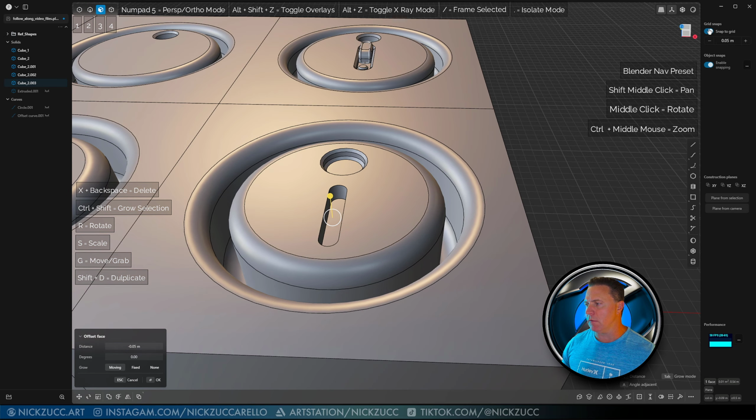We just took a very brief look at the surfacing whenever we did the duplication of that part, and it became a sheet, and then we added that patch down below and we were doing the tangency on there. So you're starting to see just a tiny bit of that. But as you get more advanced into this program, you can do more advanced surfacing, and this tangency thing is super important. So just know that this is a way to build tangency between two different curves, this bridge functionality, and it will give you this different part and this different piece that you've got here. Okay.